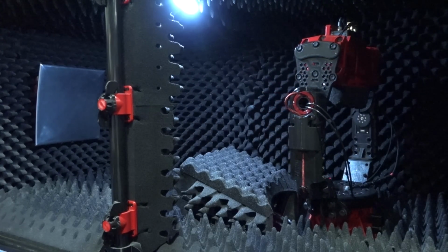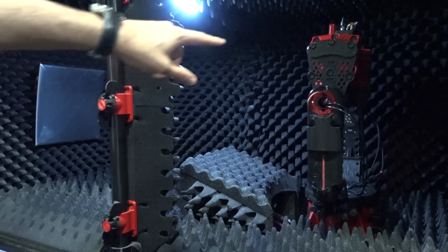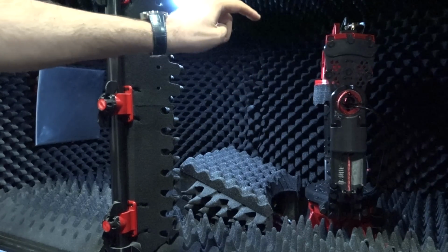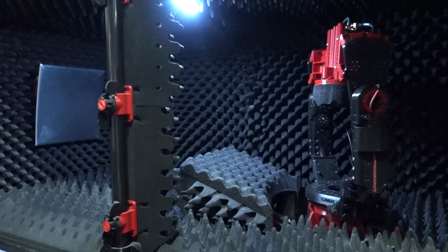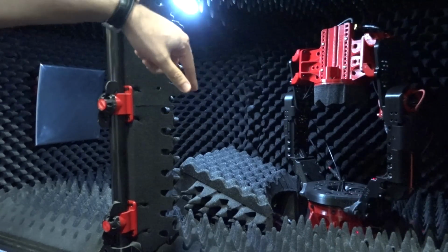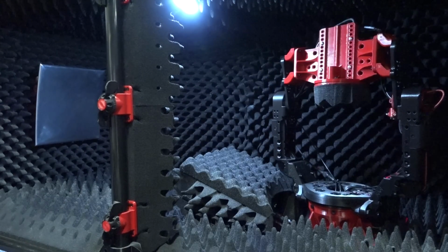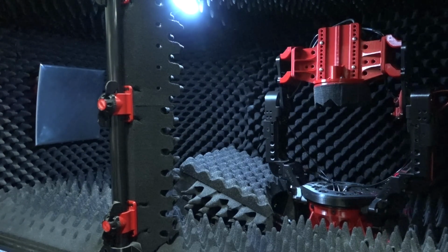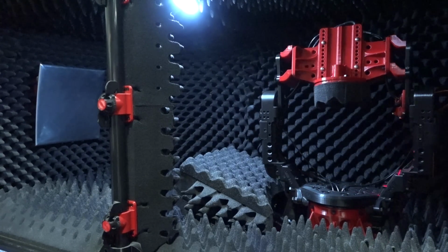So in the far back, you can see the reflector. In this particular measurement, you see the actual DUT moving around. There is a 20 dB horn antenna that is mounted in the front. This is a D-band setup. So with the movement and complete 3D rotation, and with the instrument connected to it, you get the radiation pattern profile of this particular lens that's out there.